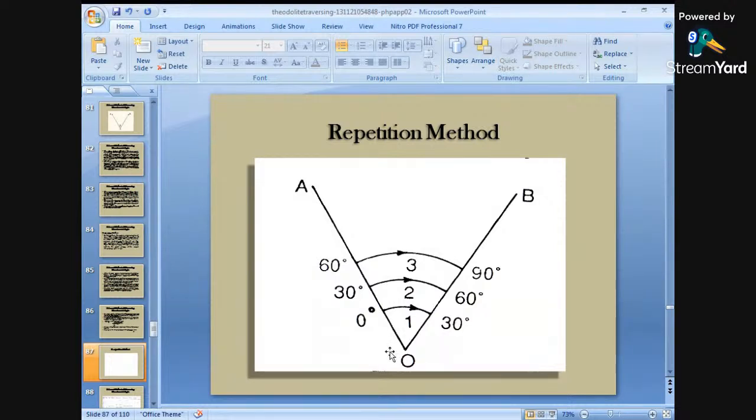Once you have bisected the point B, you will directly read the angle coming on your vernier scale. Suppose the angle is coming out to be 30 degree. You write 30 degree on your paper, that the angle AOB for the first step was 30 degree. Now again fix the upper clamp and release the lower clamp. Then turn the telescope and again bisect the ranging rod at A. Now the vernier at this point will show you the angle 30 degree at point A.